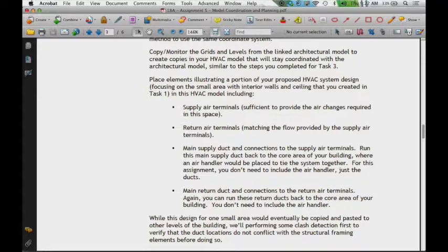Yes? So, the idea is that every floor is pretty much identical structurally and architecturally. Yeah. Well, as a gross simplification for this assignment. In reality, for the restrooms and the core, they're probably pretty similar architecturally. Structurally, as we move up through the building, we'd start typically seeing some sort of optimization where the columns would be getting smaller. The beams wouldn't necessarily be getting smaller as they go on up, but there typically would be some sort of optimization as you move up. But just as a gross simplification for what we're doing here, just assume that most floors are pretty much equivalent.